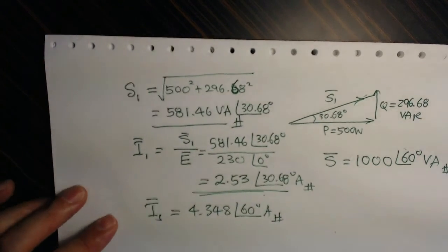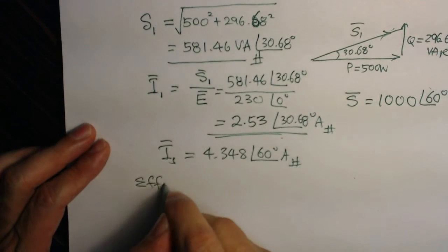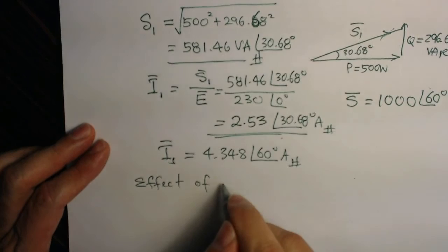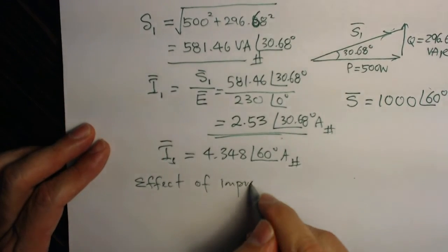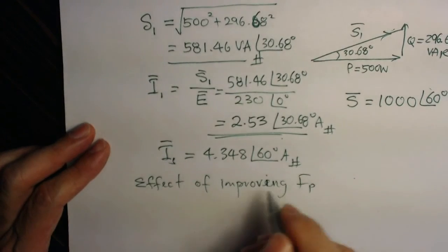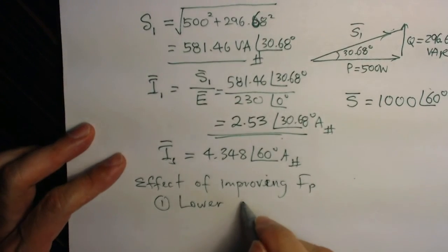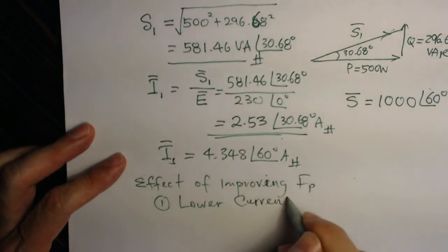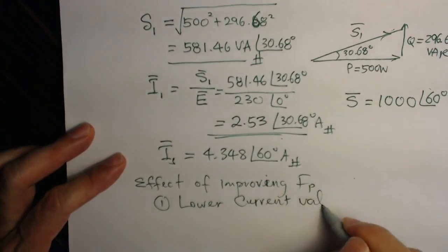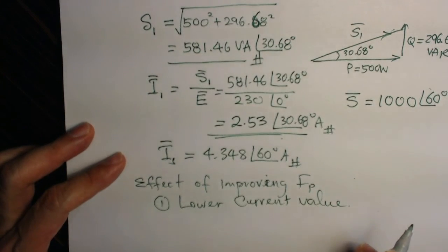So the important effect of improving the power factor is, number one, lower current value. Now, because of the lower current, it helps to lower the energy loss.